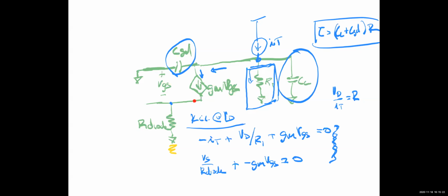So if we were to solve all four capacitors separately, because they're in parallel, we should just essentially get two answers. If you did not realize for whatever reason that CL and CGD were in parallel and you left them separate, you would simply end up with the same expression again. So you would find the same driving impedance for CL and CGD, but it wouldn't do any harm.